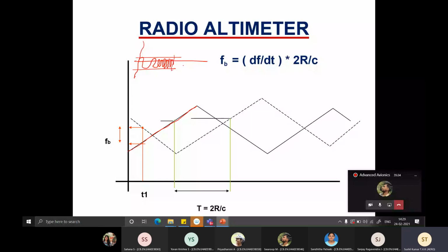The next portion, after this, you're decreasing the frequency, so gradually it starts expanding. Of course, it's not exactly what I'm drawing, but just to give you an idea that amplitude is constant whereas the frequency is changing. But the received signal will be a signal which is delayed in time, but of a frequency which was transmitted earlier. So you're just using the frequency information as a timestamp in this case.